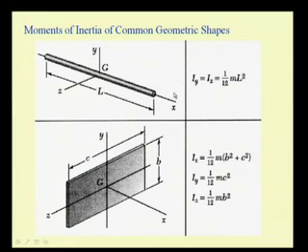Okay. So, now let us see this plate. We have already solved this example in a more detailed way. If we have these as the dimensions, let us say c and b as the width and the length of the plate, and all these frames of reference that are shown are the centroidal frames of reference. If we know the second moments with respect to these centroidal frames, then it is possible to compute with respect to any other parallel planes or axis.